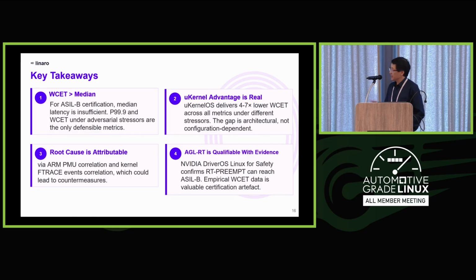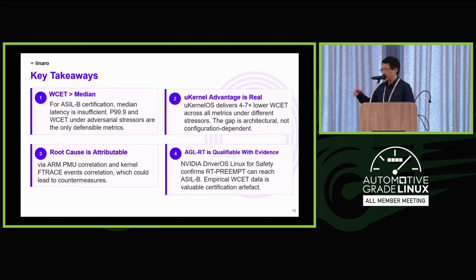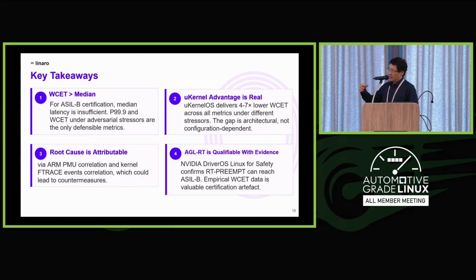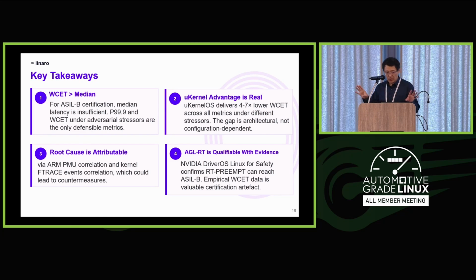And the third takeaway is that the root cause can be determined using the methodology we are proposing, using ARM performance counters plus ftrace plus post-processing, which allows us to establish this root cause mapping.